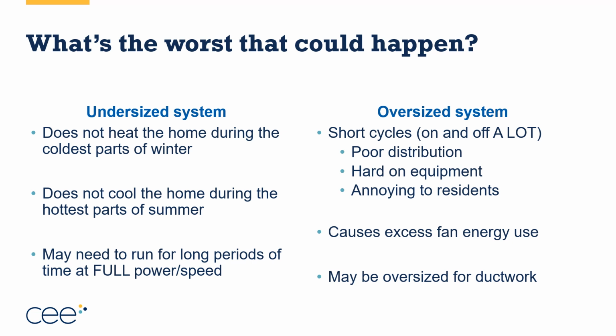For non-ECM motors, for older systems, what we call PSC motors or permanent split capacitor motors, when you're oversized for the ductwork and you get high static pressure, it doesn't increase your fan energy use so much as it lowers your ability to distribute the air throughout the home. What I'm talking about here is PSC motors have a different set of problems when they're at high static pressure. They are not designed to ramp up and deliver the air. Instead, they will continue the same amount of power usage, and they simply won't move as much air. So that can be a real problem.